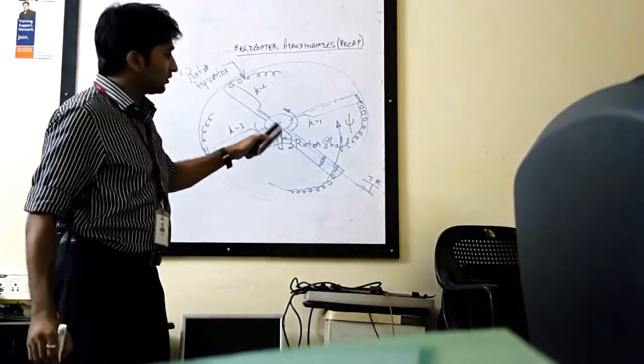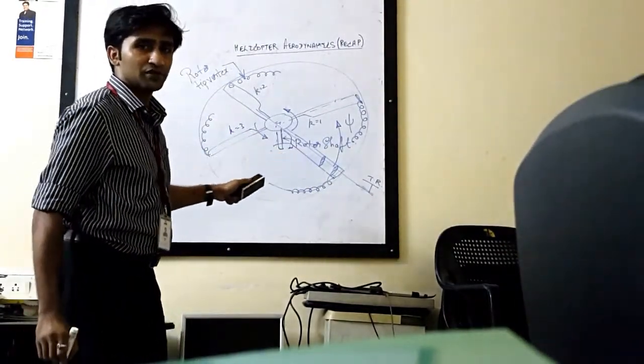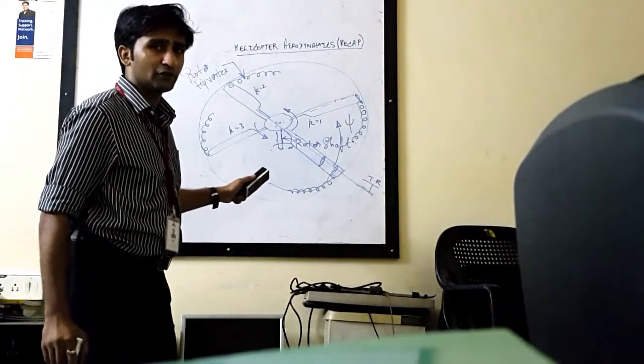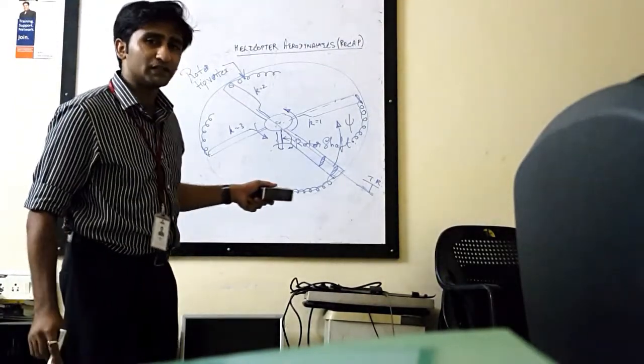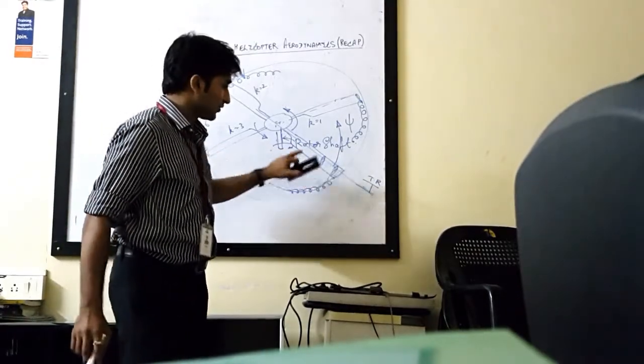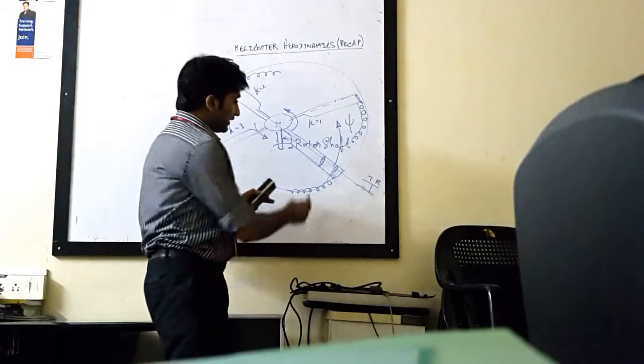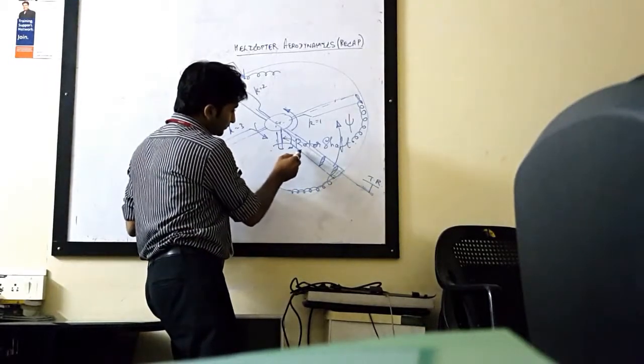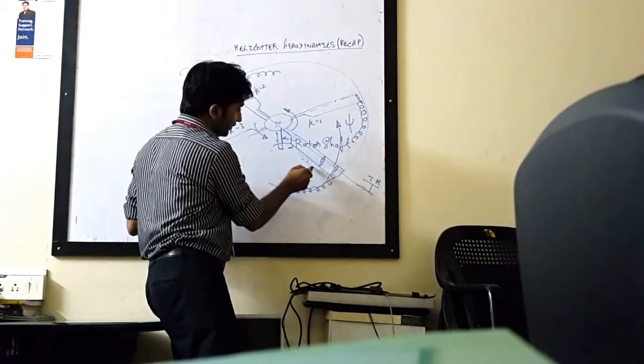Okay, now that is not the only thing which we have here, alright? What the theory of aerodynamics suggests is that any lifting body gives rise to vortices. So this is also a lifting body, not only here, right? As it tries to go up, you are going to have circulations everywhere.